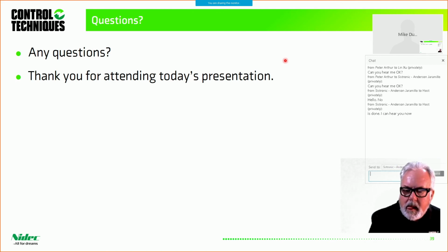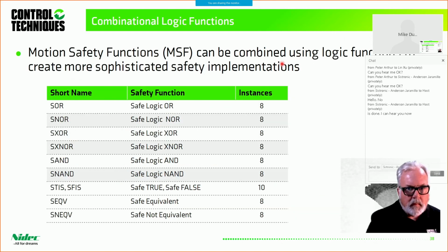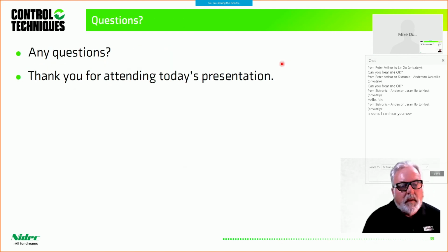And then the other thing is the encoders, just a little more clarity on the encoder stuff. There are 2 encoder ports on the module, and 2 encoder ports on the drive. You can pick and choose which ones you want to use, and that one table that you showed kind of shows all that too, the combinations and what's supported there. Yeah, that's right. And then there are also 4 inputs physically. There's actually 8 inputs. There are 4 dual-channel inputs on the module. Okay, gotcha. That's all I got.